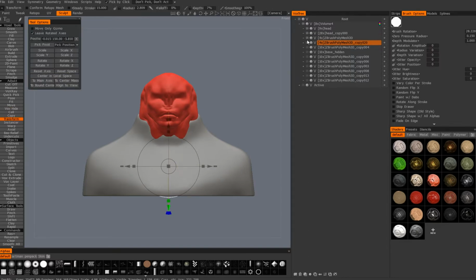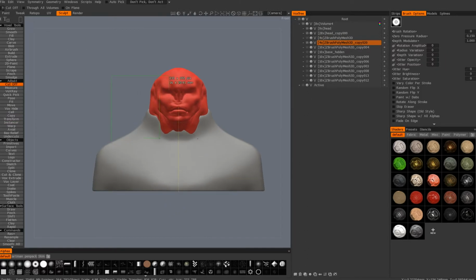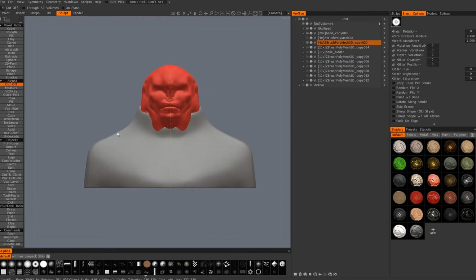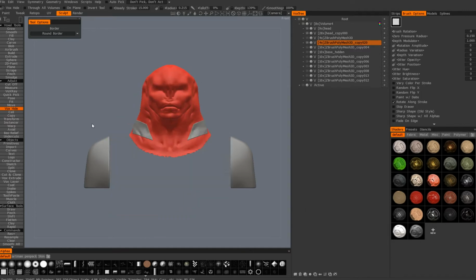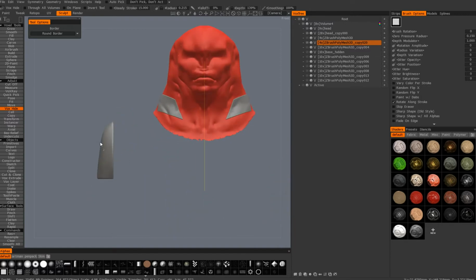So this whole thing is all about voxel height. So keep this mesh as a backup, then duplicate it, hide some stuff. And I want to make the shoulder pads, right? So I'll switch to voxel height, and I start to hide it. In that case, I always have my base, I can press Control and unhide all my bits.